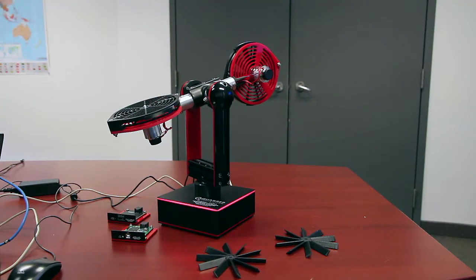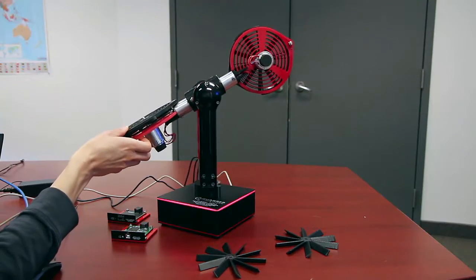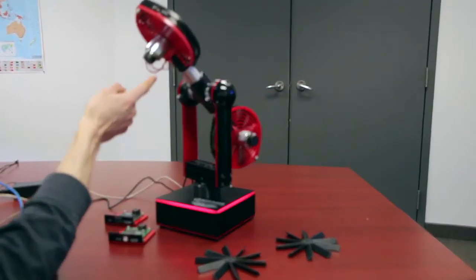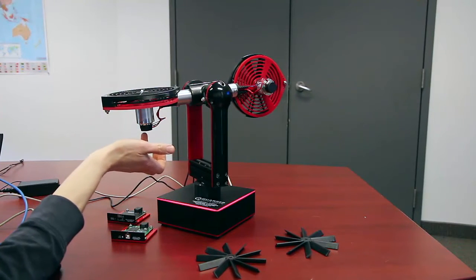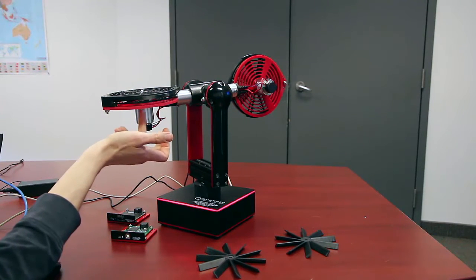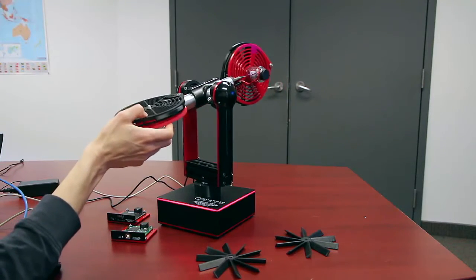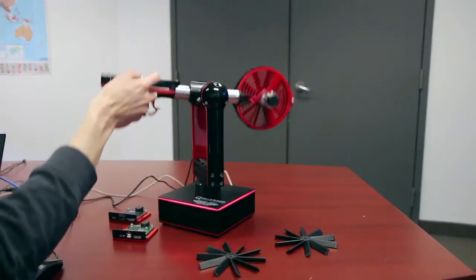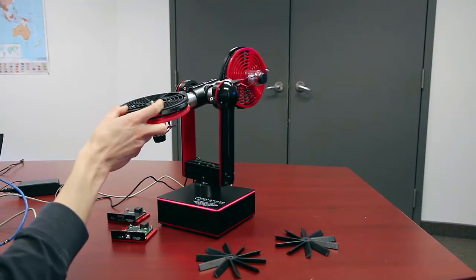Now let's talk about the sensors. We have a total of 4 encoders. As you can see, we have an encoder on each of the DC motors. We have an encoder there and an encoder here. That allows you to measure the position of the DC motor, i.e. the rotor. And we have an encoder on the yaw and the pitch, so you can measure the position of the pitch axis and of the yaw.